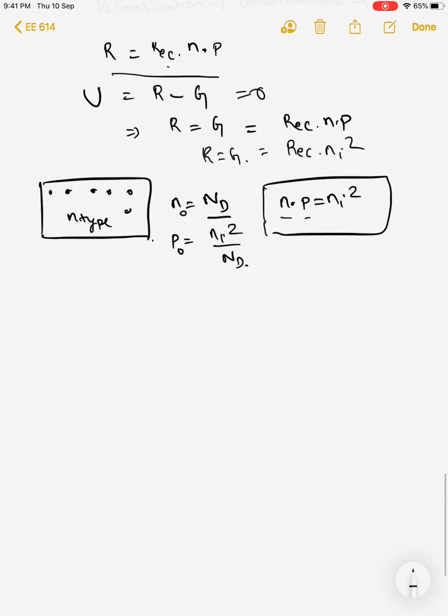And for our current discussion, I'm going to change the density of electrons and holes as n equal to n_0 plus delta n and p equal to p_0 plus delta p, where delta n and delta p are excess carrier densities that I'm going to inject, let's say by means of a generation, right? I shine some light or put a thermal pulse or whatever, and I have changed this. And in an n-type semiconductor, you know that n is almost equal to n_0, because this n is so large and this small change that I have made is insignificant in comparison,